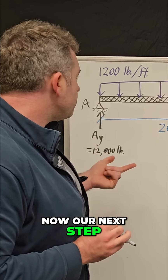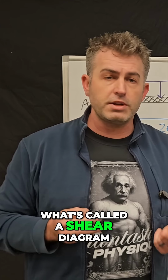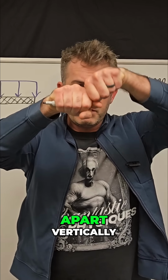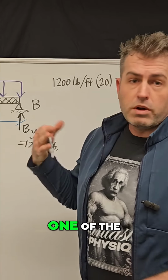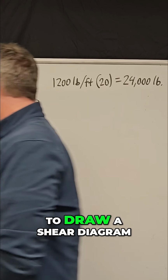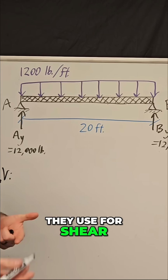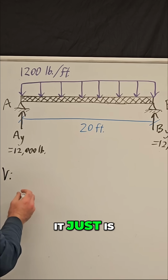So now our next step would be to do what's called a shear diagram. Shear force is essentially a force that's going to shear the beam apart vertically. And so that's one of the ways that a beam can fail. So to draw a shear diagram, I'm going to label that V. V is the symbol they use for shear. Don't ask me why, it just is.